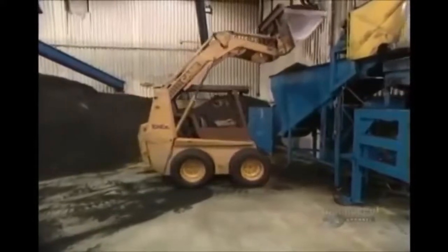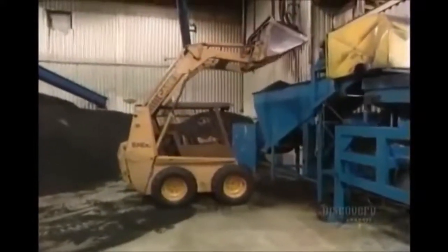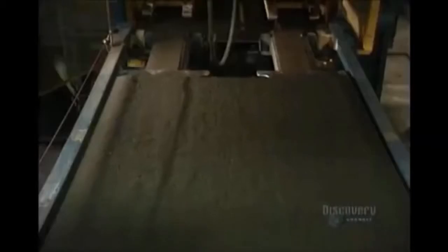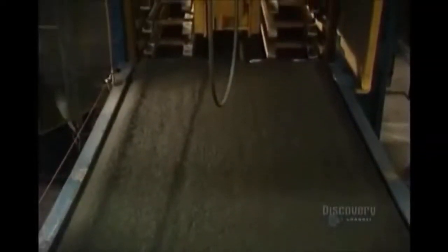This tractor feeds the secondary shredder. Grinding action produces a kind of rubber powder. The powder is spread out on these enormous molds. This mold has a length of 7 meters and a width of 1.2 meters. Thickness varies according to the product being made. The molds filled with rubber powder are stored in this loading magazine of the press. Once full, the molds are sent to the rubber mat press.